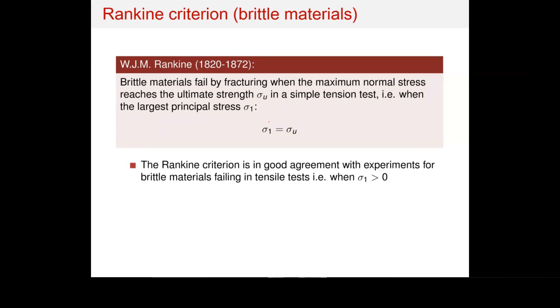Okay, so the simplest possible way to compare failure is going to be this equation here. You compare sigma 1 to sigma y, or sigma 1 to sigma ultimate. Once sigma 1 reaches sigma y, or sigma ultimate, you would know that your material has failed. There's no way that you can continue loading the material after sigma 1 has reached this point because the material has failed. So when you make your design, make sure that this condition is satisfied.